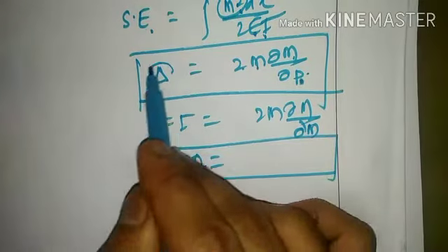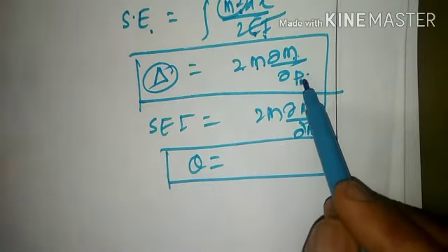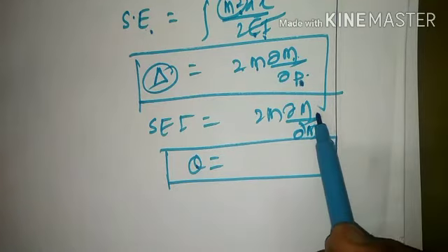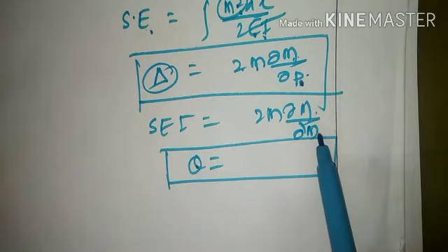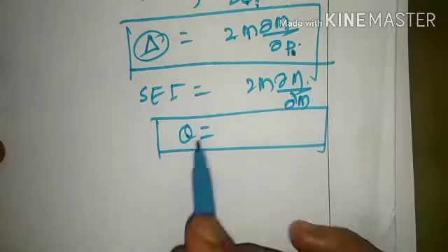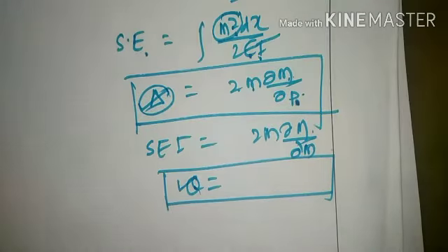If I want to find out deflection, I need to partially differentiate strain energy with respect to load. Likewise, to find out slope, I need to partially differentiate strain energy with respect to a moment. When I find this term, I will get the slope and deflection at any position.